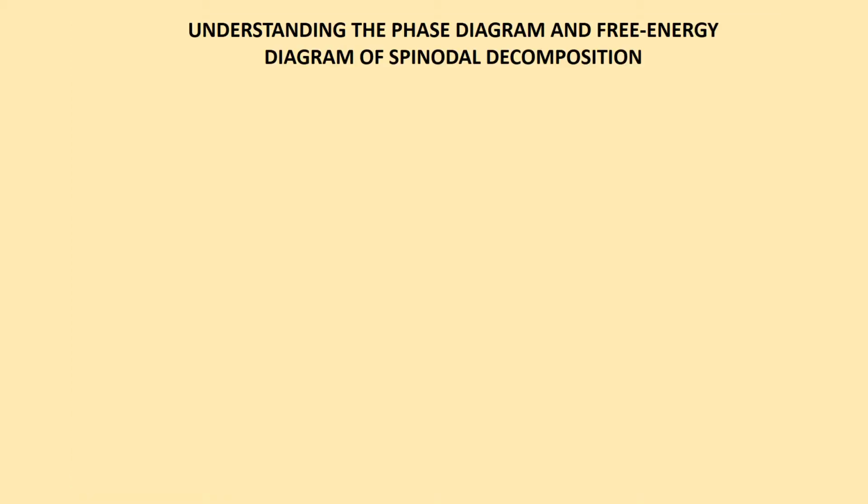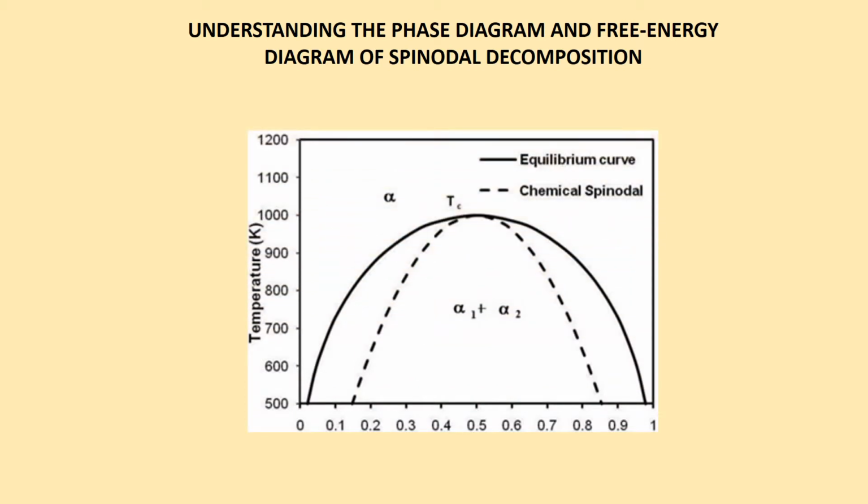As a special case of phase transformation, spinodal decomposition can be illustrated on a phase diagram exhibiting a miscibility gap. This phase separation occurs whenever a material transitions into the unstable region of the phase diagram. The boundary of the unstable region, sometimes referred to as the binodal or the coexistence curve, is found by performing a common tangent construction of the free energy diagram. Inside the binodal is a region called the spinodal, which is found by determining where the curvature of the free energy curve is negative. The binodal and spinodal meet at the critical point.